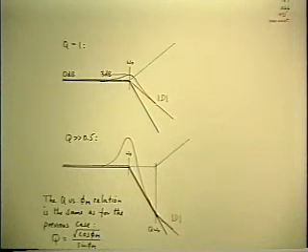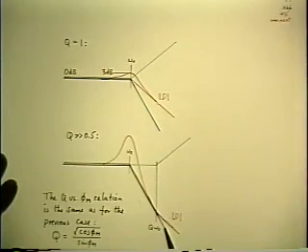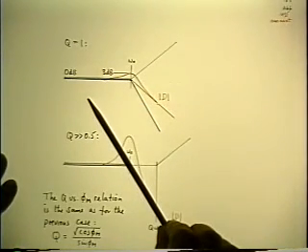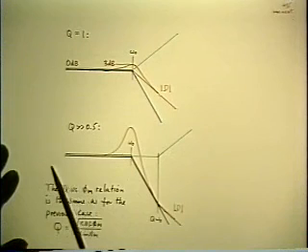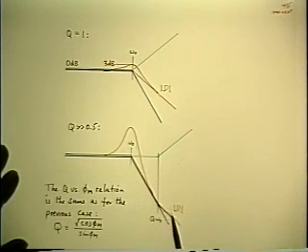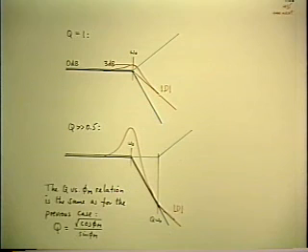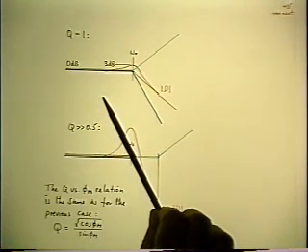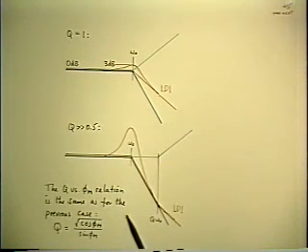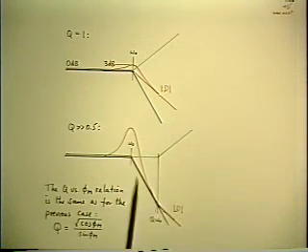And if the corner moves out even further than that, if the 0 moves out further, where you've already crossed over on the double slope, then the closed loop response peaks up significantly as well, and then turns around and follows the T after you encounter the 0. And all that is saying is the compensating 0 was too far out to do any good. You've already crossed over on the double slope with a very small phase margin, which is what causes the big peak. And the 0 doesn't do anything till out here, and it's too late.